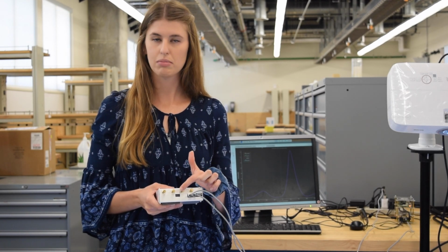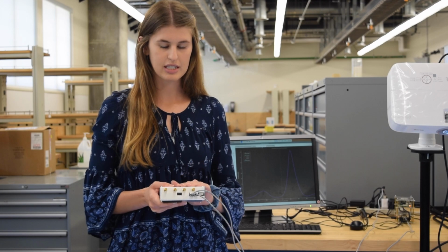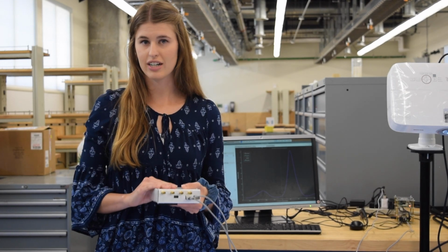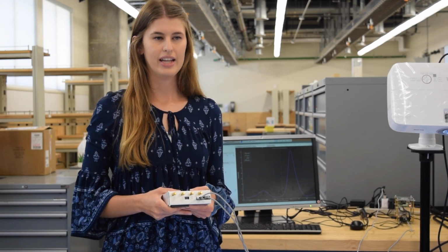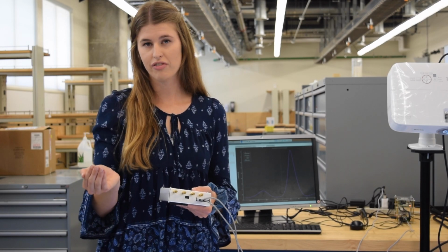So here's where we plug in the antennas with an SMA cable, and this is then connected to a Raspberry Pi, and the Raspberry Pi runs software that we can first use to synchronize this so that the phase is in sync with each other and all the samples are calibrated. And then we can set it to operate at 915 megahertz.